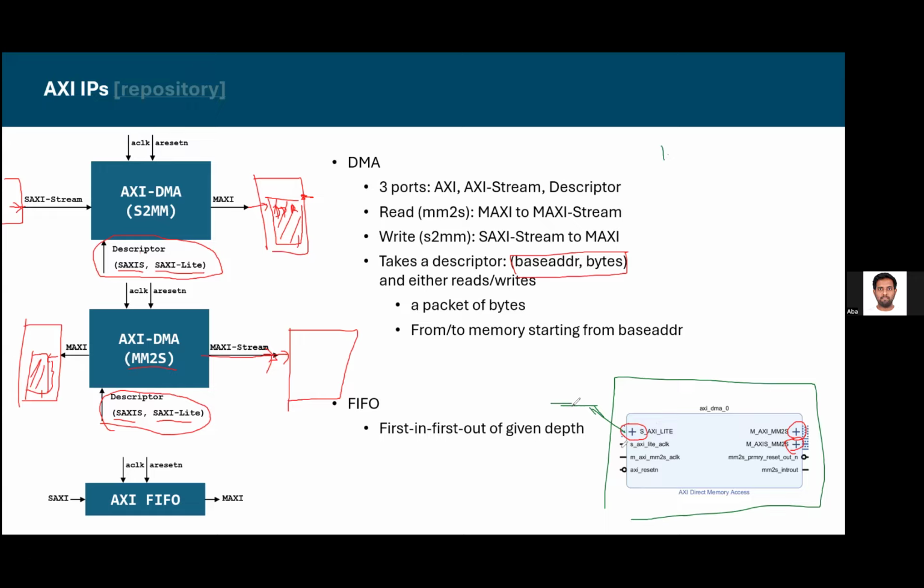Especially from the CPU. Or else you can actually control this from your own module if you want, but then you have to write sort of an AXI Lite manager, which we didn't want to do, and that is even more complicated. So if you know how you are going to increment this access stream, or how you are going to implement your addresses, and you know this from the RTL side, from the Verilog side, if you have your own modules which can do that, then it's much easier to use the AXI stream port. That way you can keep giving data as soon as you can.